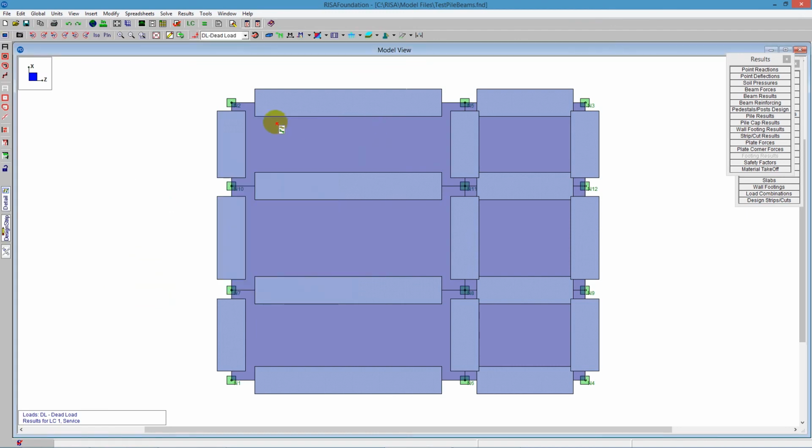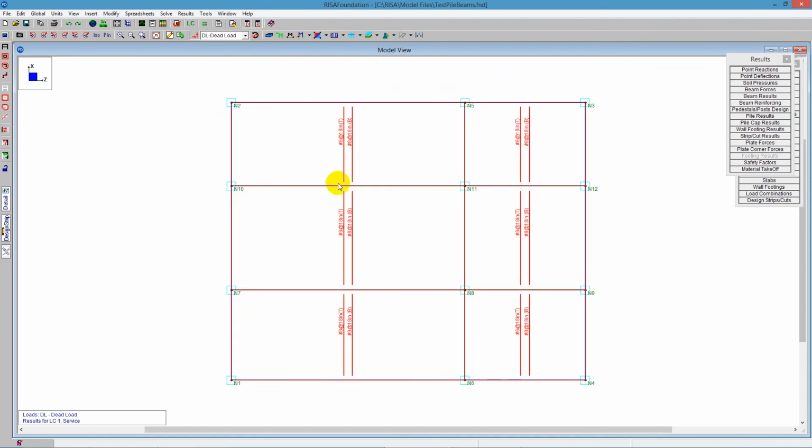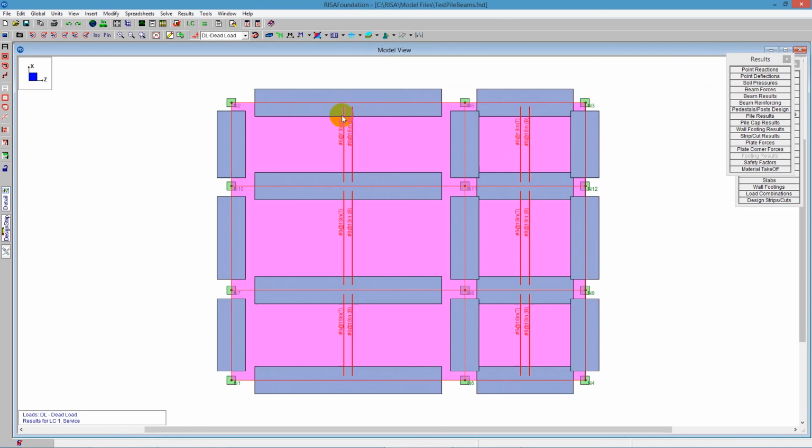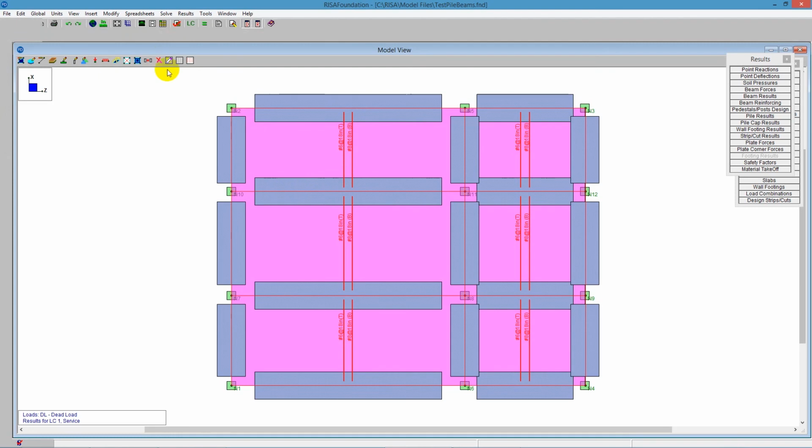The other thing you'd be seeing here is putting in your design strips. So if I go ahead and look at my design strip for a second here, I'm going to go back unrendered. I've drawn in design strips here from center line point to center line point. But if we remember, that is an actual overlap at that point. So those beams are submeshed directly to the slab, but since I have a design strip defined directly to the center line, there's just a bit of overlap between those. So it's not something to worry about, but if you had highly reinforced beams, you may not need to have that design strip drawn directly to the center line because you already have accounted for all the forces at that location. So you could go ahead and delete that design strip and draw it a little differently here.